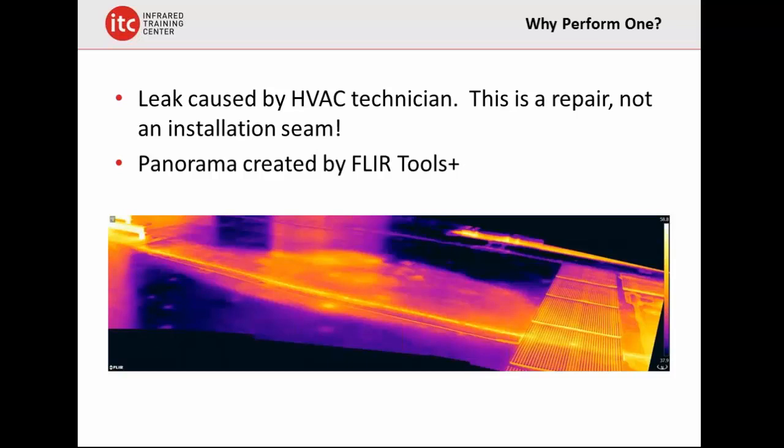Well, that's a good point that you bring up, because we get this question in class sometimes where people ask, can I use infrared to find where the leak is and patch the leak? And that's really not the issue here. That has to come out. Just because you fix the hole doesn't mean that you get rid of the water. The water's still there.